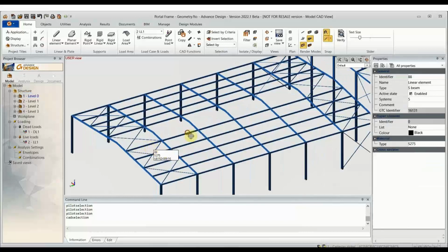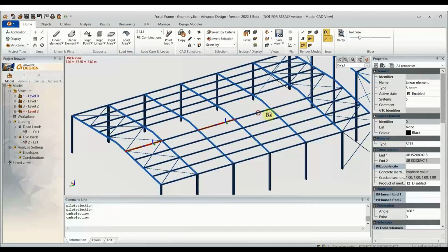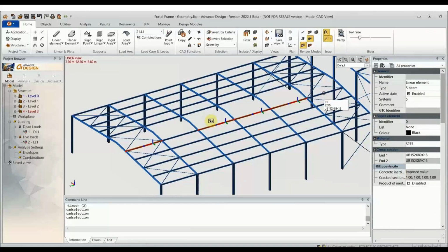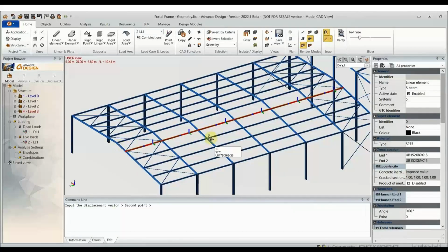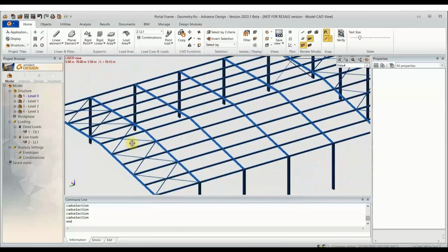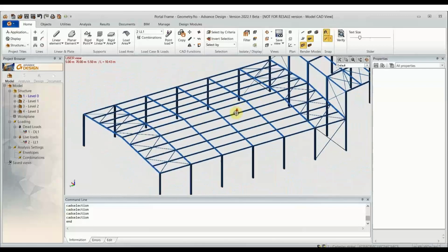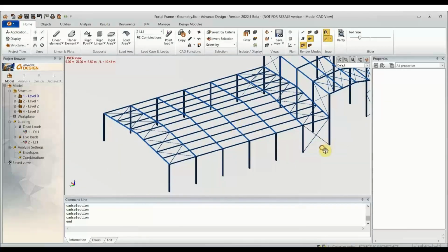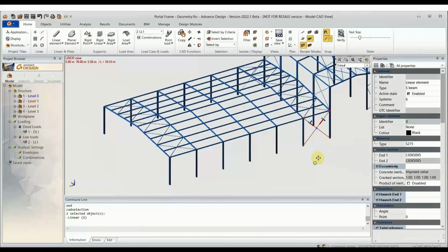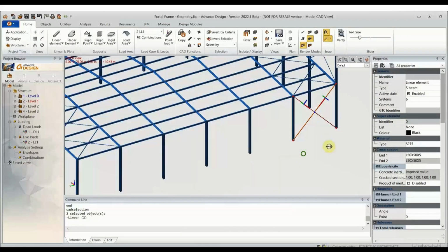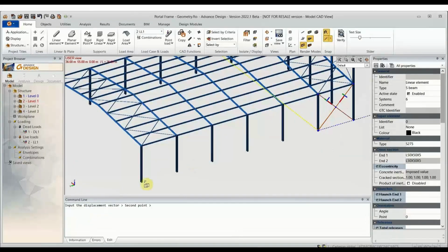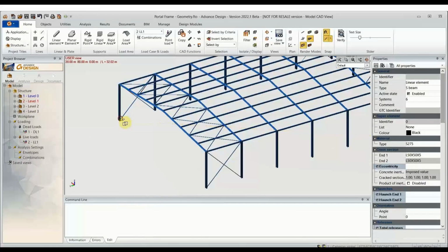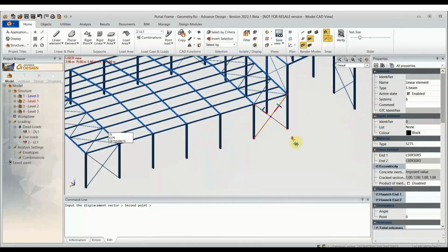Let's start off with this purlin then. We need to add a purlin over the ridge here to complete this. So I'll just pick up these and simply transfer these across. There we go, 1, 2, 3, and we're there. So we've got the central purlin there. And the other thing we want to do is add a set of bracing to the end bays here. So again, very simple, just within a few clicks, select my brace and pop it in the end bay there. So that's some changes there.